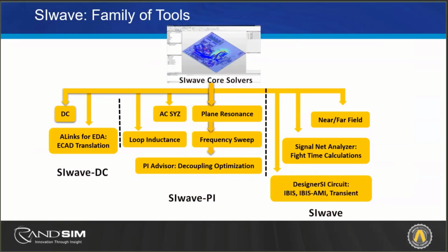If you have a connector, you can then incorporate it with HFSS and solve for the connector and the trace level within HFSS, looking at S parameters, for example. This is a pretty common workflow, but you'll have a good understanding of not only how your connector works, but also how your traces are impacted by that connector.